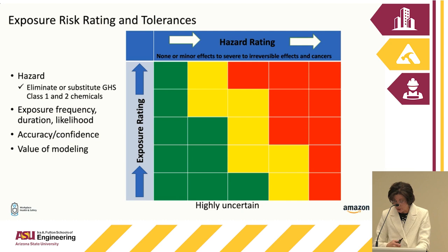And then, when you do have them, you have to establish what that risk is going to be for the emissions. So if I have chemical agents that have authoritative OELs, I'm going to probably want to control the emissions coming from that, if I have a worker standing right at the machine, to probably 10% of that occupational exposure limit, and I have to be confident to about 95%. That's a heck of a lift. That's a heck of a lift for industrial hygienists that have to figure out how to design what those emission standards are going to be from that equipment.